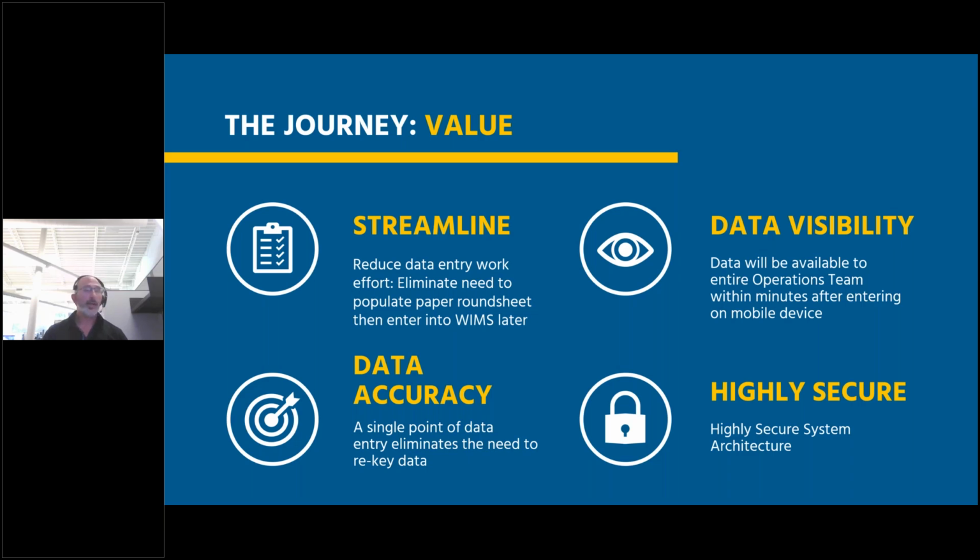When you get time, key it into WIMS, wait for that synchronization to get to the various dashboards to make it available to the operational management across the enterprise. What happens now? Well, the operator walks around the WRF, the plant, with a mobile phone, with the Rio mobile app. And as they enter the round sheet data, it goes right into WIMS automatically, right? And then once it's in WIMS, it's pretty much instantaneously available to the operational management without them having to wait.